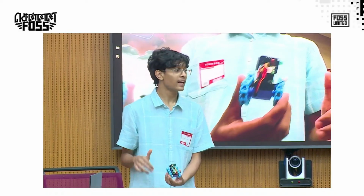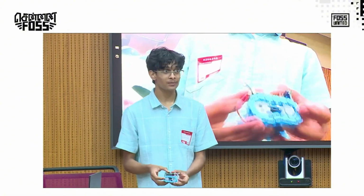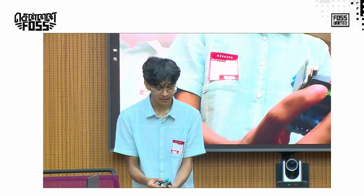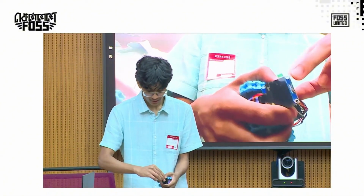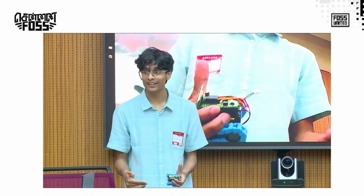Has everyone completed this step? Yes? Okay. The most important step: again, make sure the yellow wires, you see here, are towards the labeled pins, S1, S2, S3. If you don't do this, the thing is going to burn. So I'll come over to each one of you and ensure that you have done this step correctly, because we don't want the servo to burn.